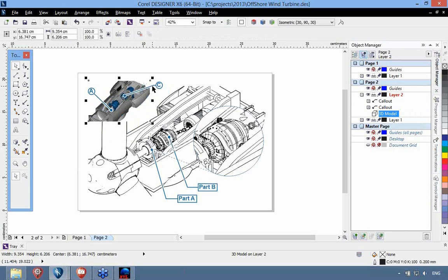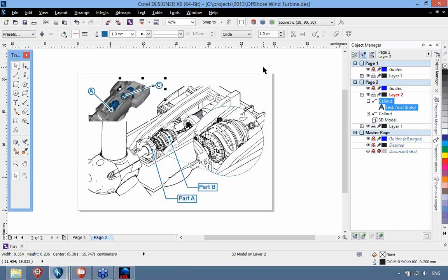You can change that to make the whole callout follow the source objects, the origins. So that's something that you can specify in here to move the whole callout, or to only move the leader line and the starting point of the leader line.